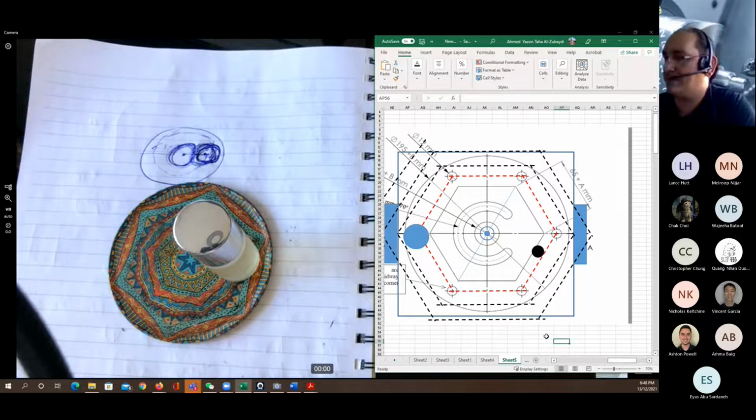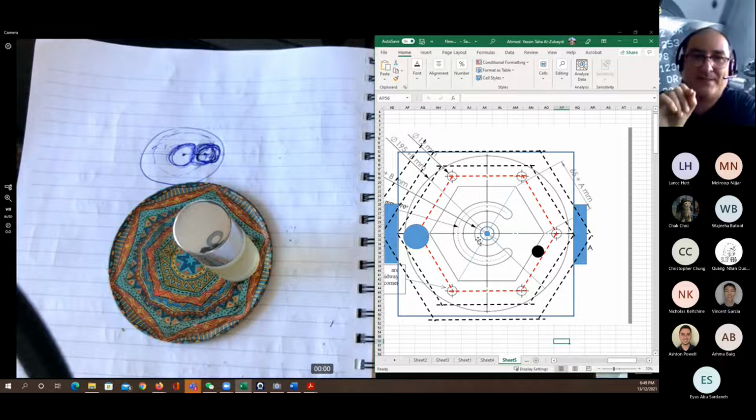No, it's not going to be the diameter of the tool. Okay, now we said that this side is offset by 6 millimeter. This side is offset by 6 millimeter. So we have a 12. So the diameter of the blue circle is going to be 13 millimeters. So it's just 1 millimeter only larger than the diameter of the cutting tool.